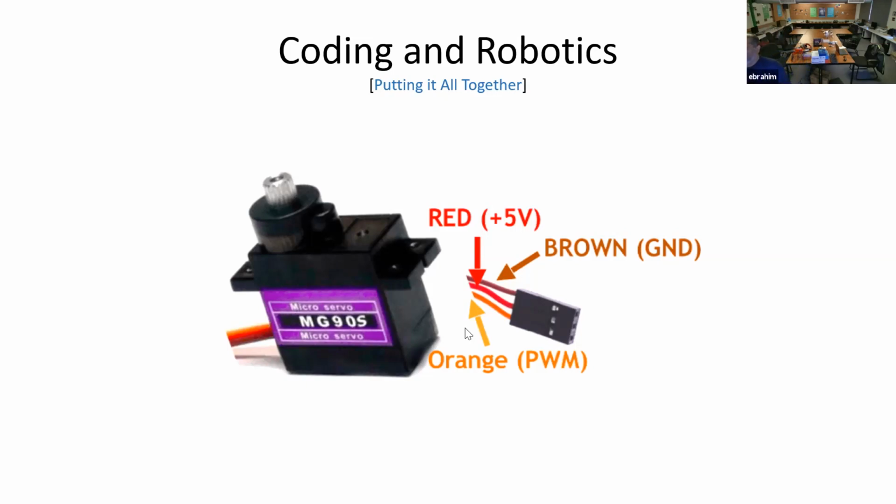Now, PWM has been around a long, long time. You see it a lot in motor cars right now. You see it a lot in your house lighting as well. We don't actually keep our lights on all the time. Internally there's a logic that switches it on and off very fast, and it appears like it's on. So that's basically how PWM works.